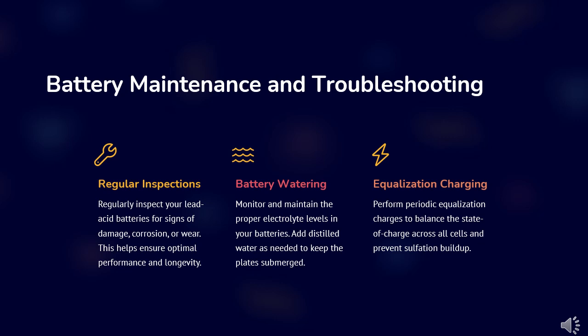Regular maintenance is vital to keep these batteries clean and working optimally. Inspections every 2 to 4 weeks, maintaining proper water levels, and cleaning terminals are crucial for these batteries. Following the manufacturer guidelines for charging lead acid batteries will ensure optimal performance and longevity.